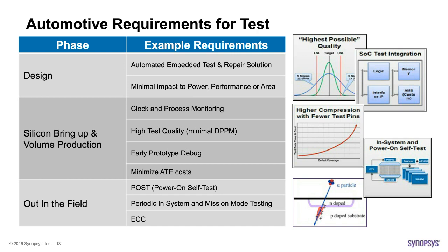And for that, we don't only take care of the manufacturing test, but rather the test is something that starts early on in the design stage and ends up being utilized in the field. So in the design stage, we start by building automated capabilities to incorporate the DFT and the built-in self-test engines from the smallest building blocks and moving forward while taking care of the area, the performance, the power.